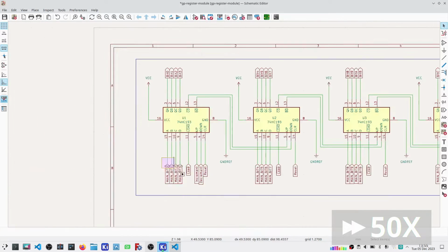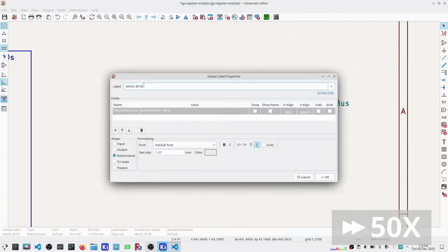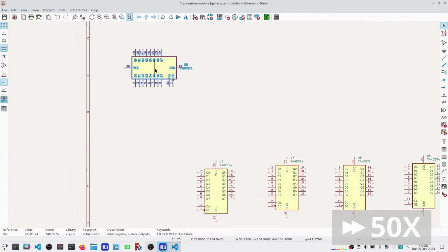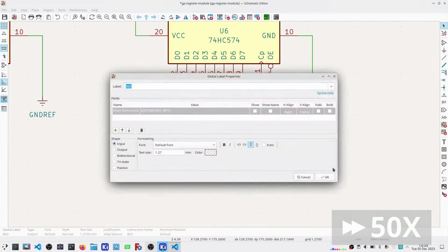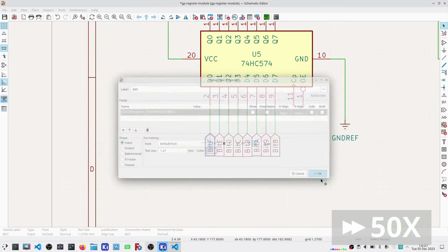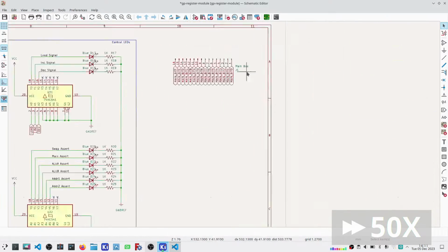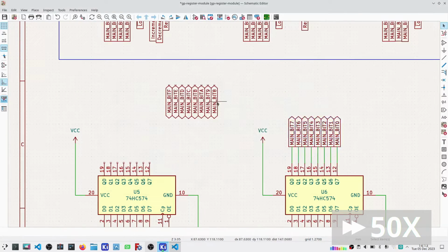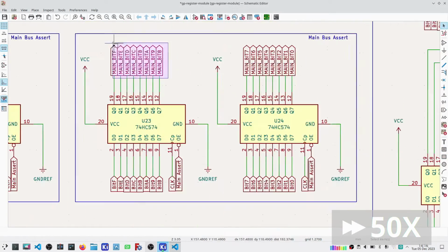Here I am working on the module I/O. Now, data coming in only comes in off the main bus, so that is ultimately going to be bidirectional because I can also push data back out onto that bus. But outputs, there's 2 outputs which can assert out onto the main bus, and then I've got 4 additional buses, ALU-A, ALU-B, address bus 1, address bus 2. Plus I need something for the control signals.